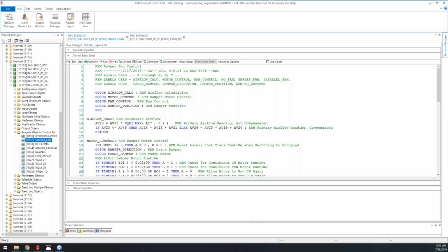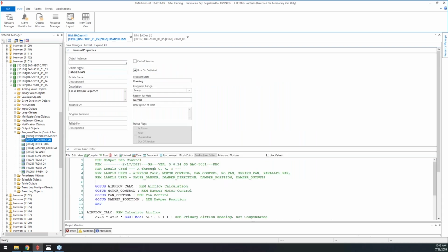A program object, we call them object oriented, so each one of these is a program object. Make sure you label that program when you start doing some code writing. I've seen whole controllers with no labels, and so I don't know what's inside that. To label it, you have to come up here to these general properties chevron, expand it, and right here's where you add the name.